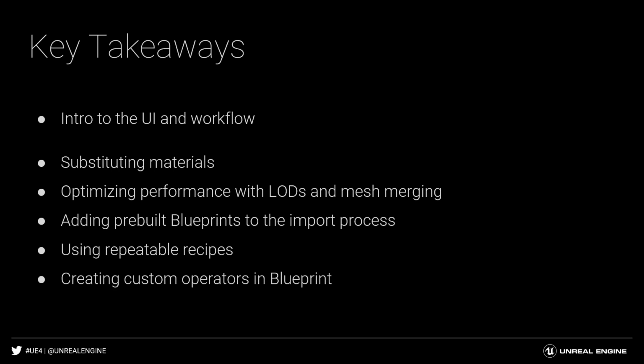All right, so to get started, we need to do a few things first. First of all, we're going to need to get a couple of plugins installed. You're going to need plugins for Datasmith as well as the Data Prep tool. Now, Datasmith and Data Prep plugins, we're going to need those for Unreal Engine, but we're also going to need to set up some plugins for our tools. And today we're going to be working with Revit, Rhino 3D, as well as Maya.